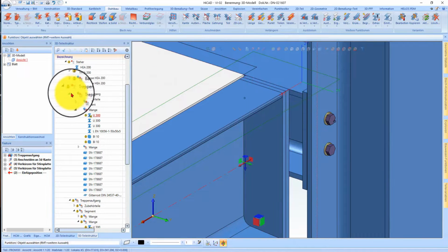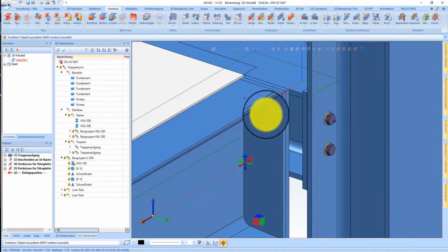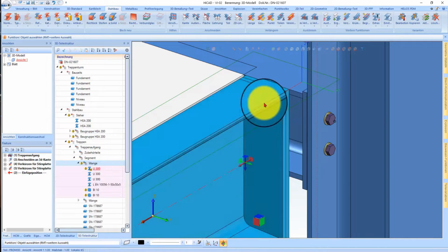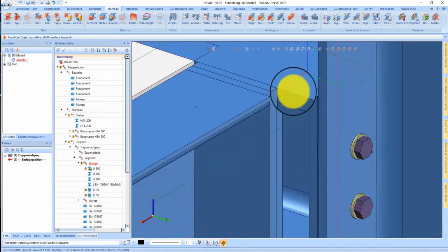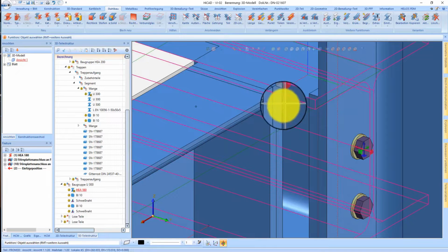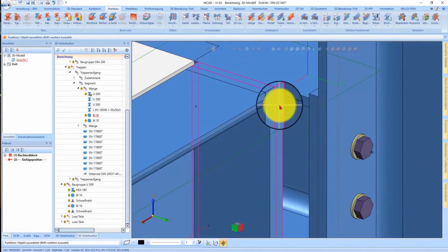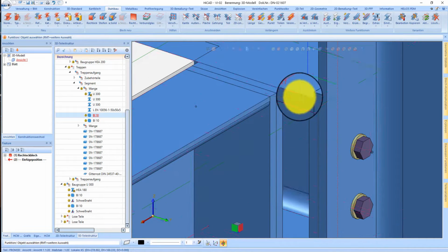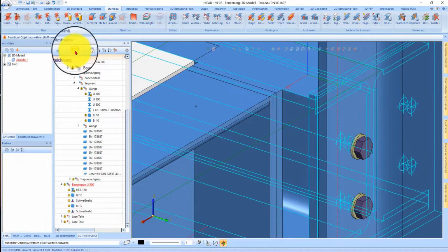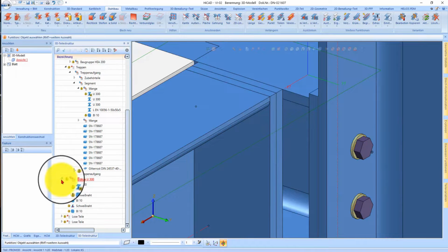That means now comes a crucial point that has been asked repeatedly. Actually, I mistakenly have this rear plate with this plate here, but this should come to this plate, to this beam. That means I simply need to change the structure here. I can simply cut out here, for example, then select the assembly, and here I say, for example, insert.